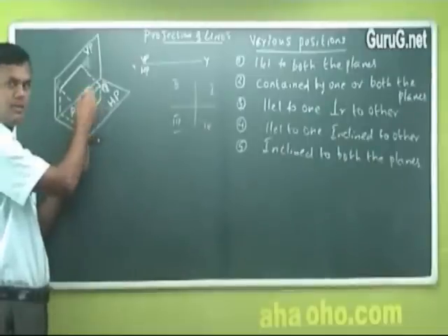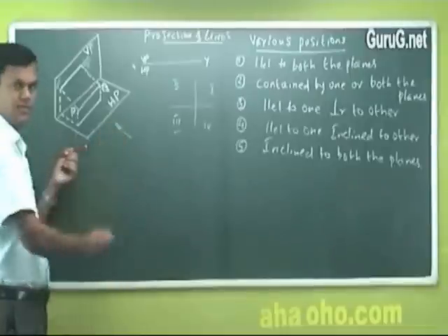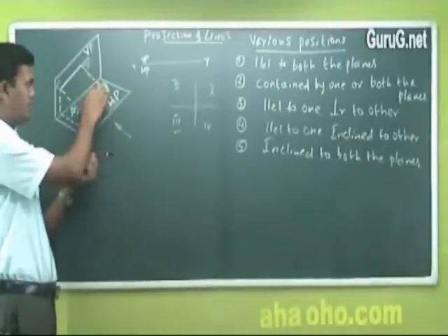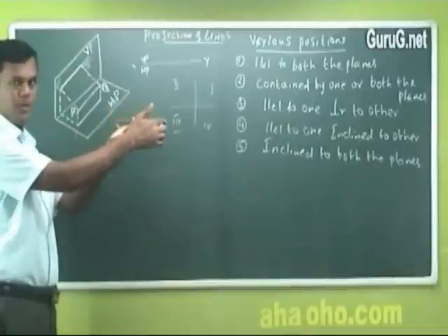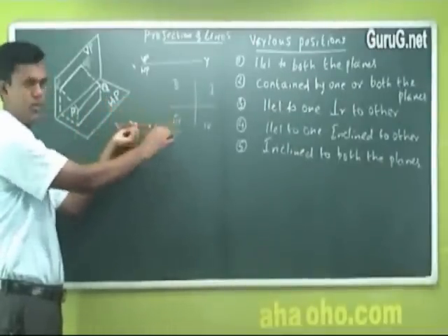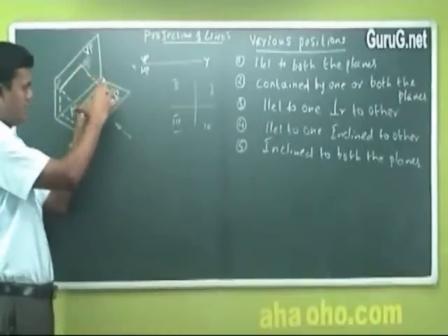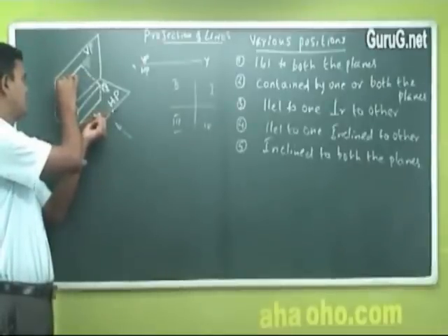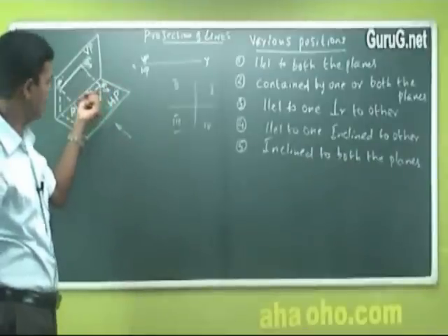For this line's front view, whatever you see from here, PQ can be seen directly. Actually, I am holding the pencil like this, parallel, with point P and Q. In the front view it is directly a straight line, point P here and Q here. That's what I have written. This is actually the pencil position, but the line's front view is drawn in VP. So I'll write one point as P dash and this will be Q dash. This is how we denote it, for the front view.